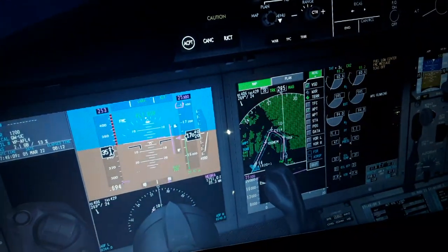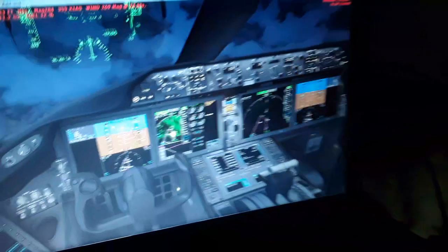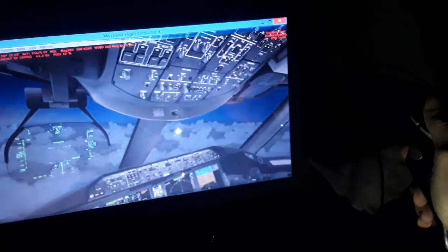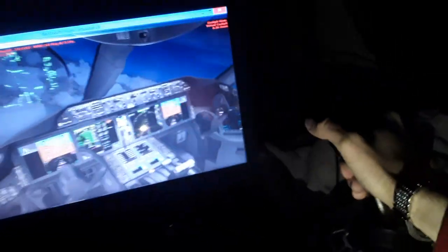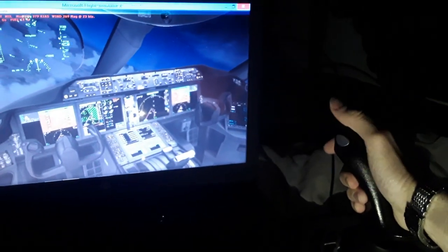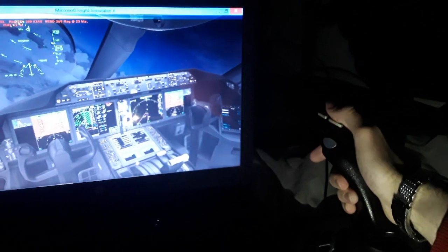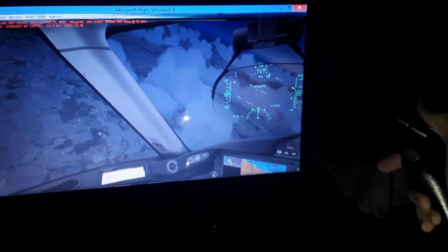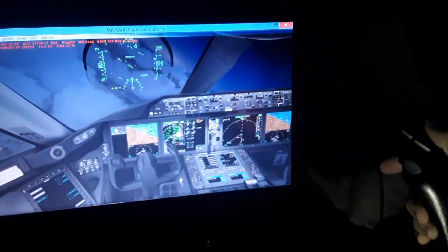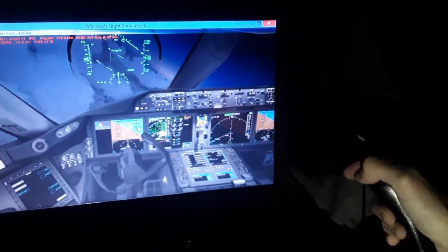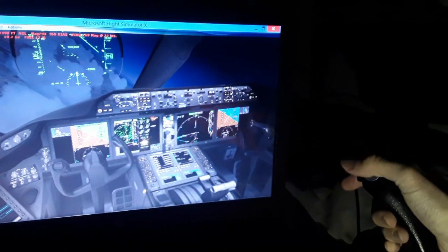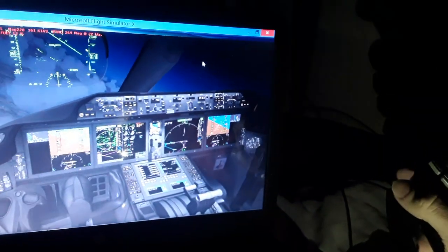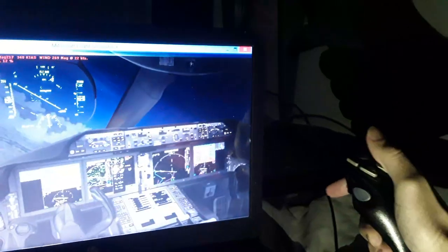we have max 0.695. We need to start turning now. Idle thrust over here. So we need to start the turn now. For the approach, use some left rudder. Keep descending. So we pay attention to the instruments as we descend like this. Let's use maybe speed brakes here. Slow us down. Accelerate the descent.